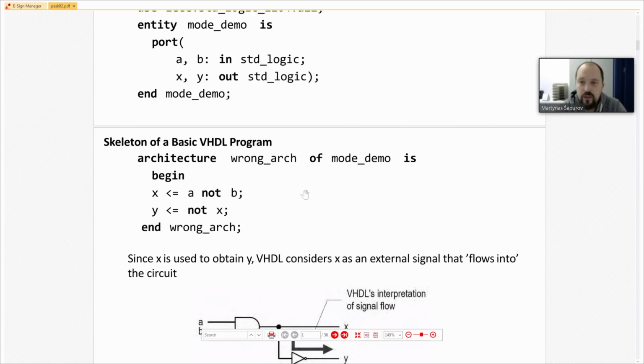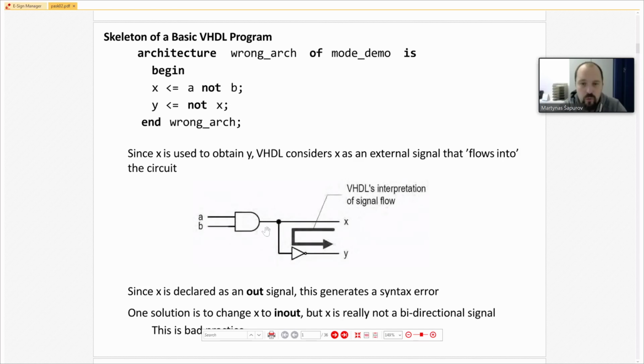So your synthesizer will analyze the circuit like this, and it will directly connect X to the output Y. Instead of calculating the A and B value and transferring it somewhere, it will connect two outputs together. So it won't work. Usually it can cause hazardous operations, so the synthesizer will declare an error in your design and won't compile or synthesize that design.